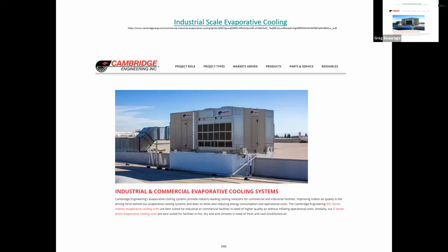Right, so it's a process with no condenser. And then you use heat in that process to remove the ammonia from the absorbent material. So you use an absorbent so it's in a liquid state. It evaporates, that cools. It evaporates and goes into an absorbent, like you can use activated carbon, or you could use lithium salts.